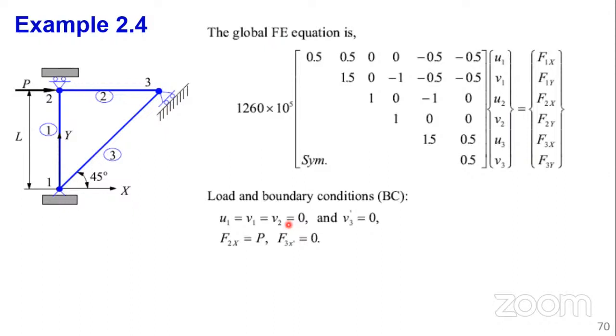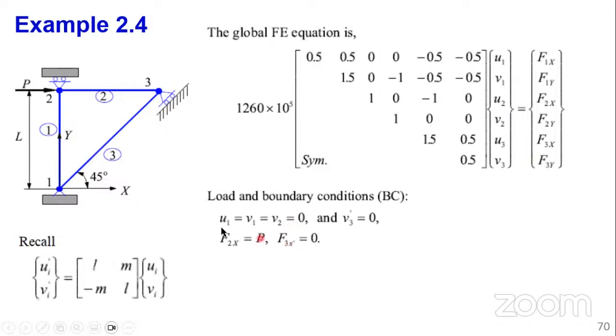Because in reality, what we are saying is that our structure is floating in space, what we call rigid body motion. Right. Now, with that in mind, something you have to note here: we go back to the elemental scale because we want to transform from element to global. This is the equation we started with at the elemental scale. This is the first derivation, transforming a node from local to global.